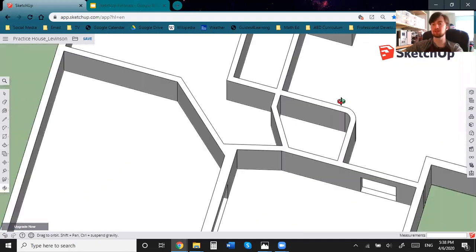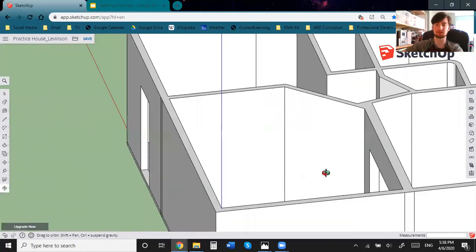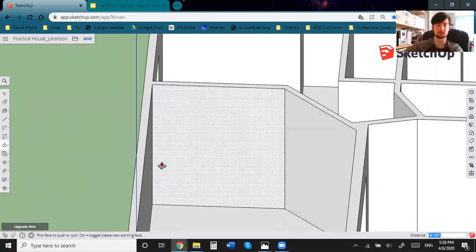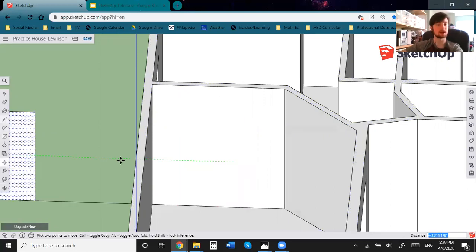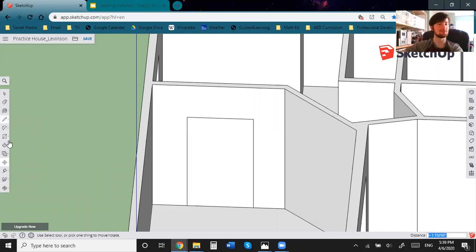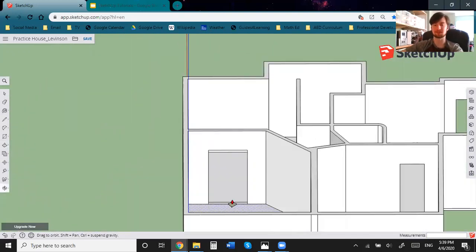Okay, so at this point you likely get the idea of how to go about doing something like this. I'll make one more door opening, or this isn't a door, this is just a wall opening, and then we'll try out some windows as well. So click on the rectangle, click on the edge. This one's also big, we'll say 4 feet across, comma 7 feet. And I'll move this to the center, and oh, I moved that off by accident, and push pull, push that rectangle through. So at this point you probably very well get the idea of how to go about doing this.